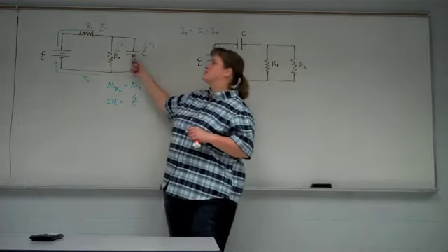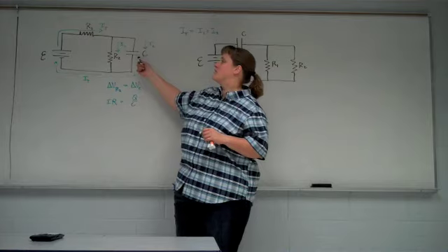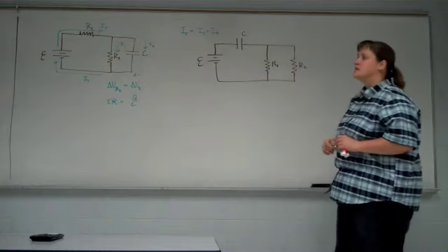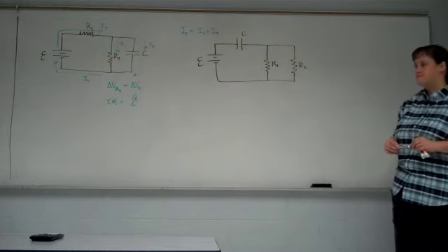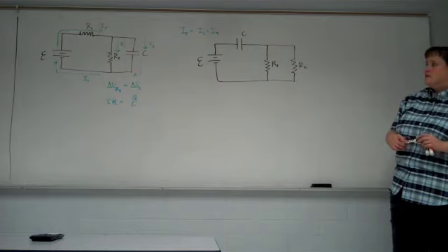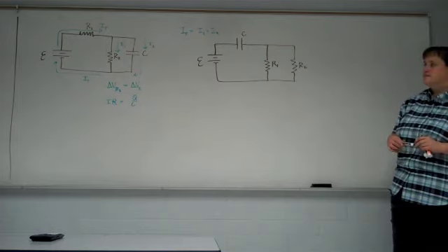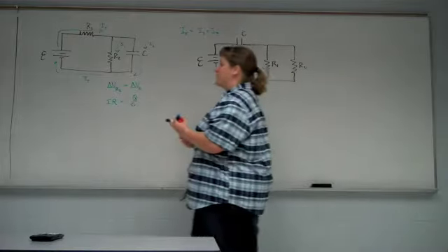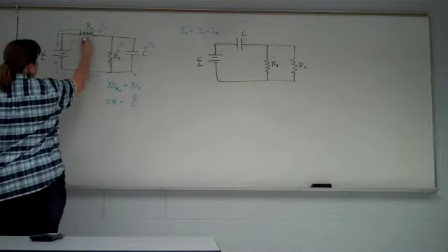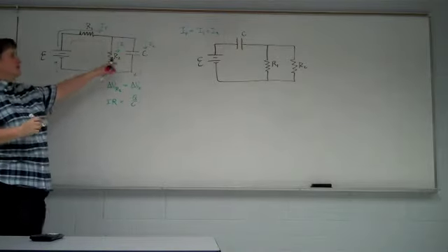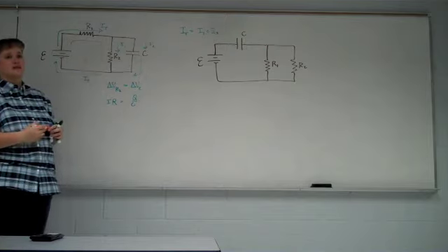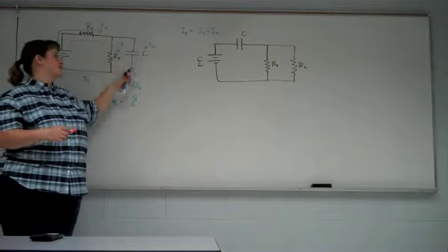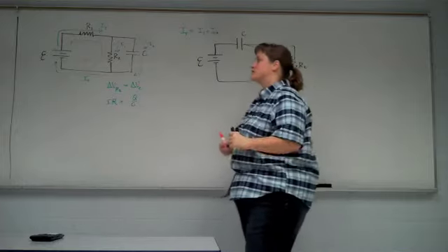But over here, the capacitor is not in the main line. So it will reach a maximum voltage. At that point, there will still be current, it just will no longer be changing. So there will be the same flow of current, but it will just be going through the path of R2. Correct. Exactly right. So at that point, current will just be going that way. Won't go along that other branch. That's exactly right. So the capacitor stops the current in the branch it is in when it is fully charged.